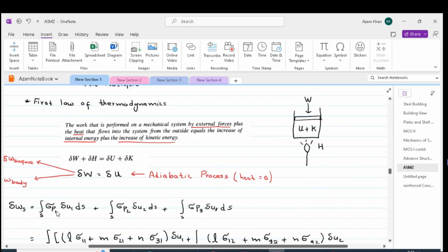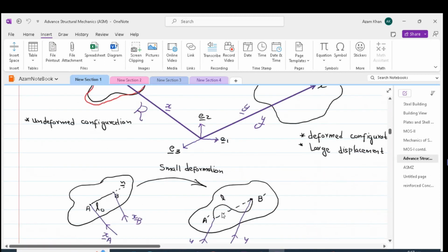We don't consider any variation in the stress component at any point. Therefore, we take the stress component as the full magnitude at a point. Only variations in the displacements are considered. It is important to note that the displacement variations within the body are completely arbitrary, and every particle within the body will occupy a unique position, whether before deformation or after deformation.